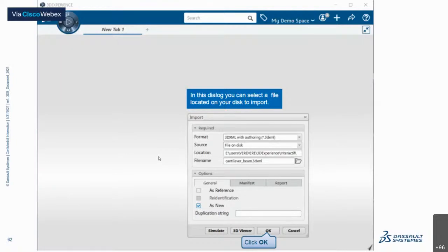That is, if you put my name, like Siddharth, and a product, the product which will be created in your document will be the Siddharth cantilever beam. So that's how you can do it. You can either use your name or you can give a standard name which is being followed. It's recommended to import as a new, since you can then make any changes on your model too.